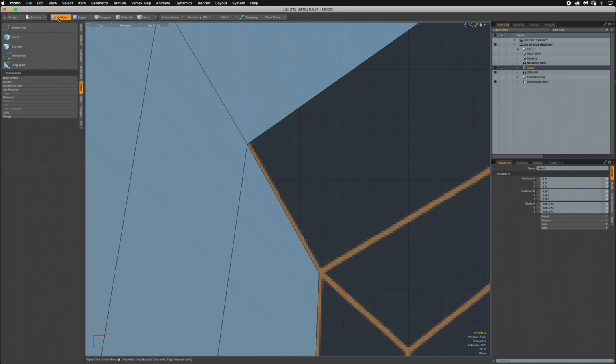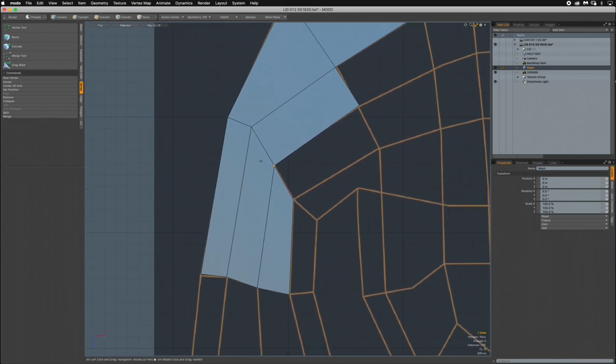So we go to vertices, select the two vertices. When you select them, it'll tell you how many vertices you have. If you see the numbers as you select vertices, they'll tell you. So when you're selecting two in the area, make sure there's two, you'll see it here, and then just join that.